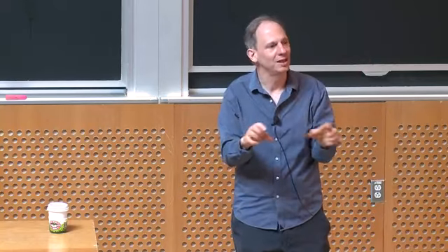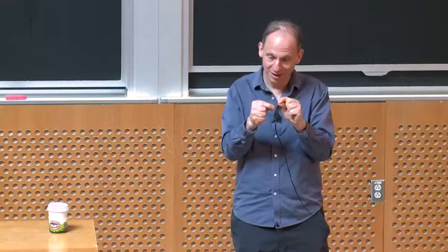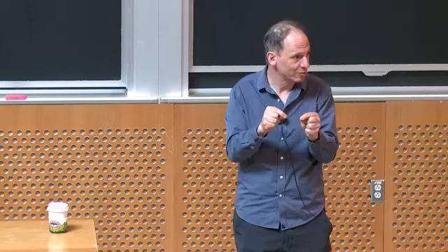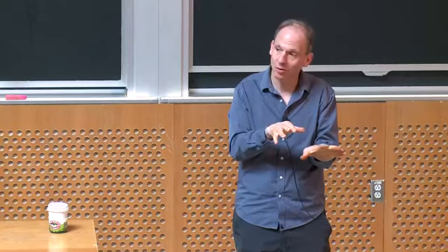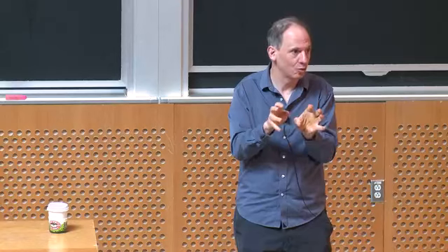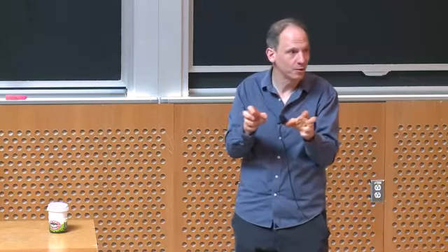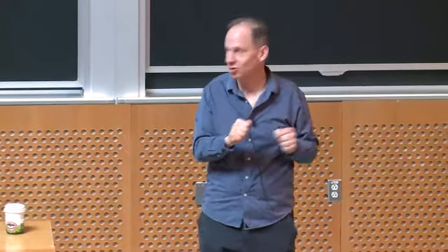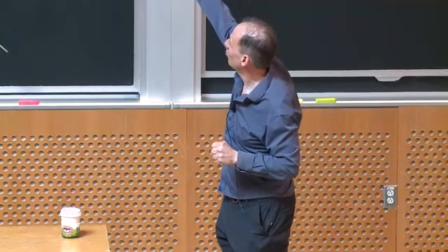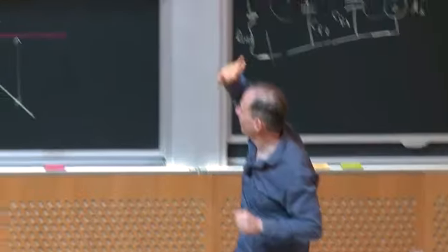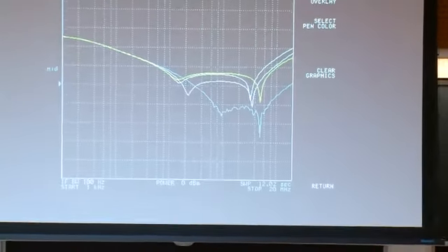Try to reduce the parasitics by being very careful about how you lay out your components. Low inductance insertion, low capacitance across the components, and that will go a long way towards getting around weird anomalous behavior and getting to be as good as you can. And even when you do that and you're getting some worse performance, getting worse around 20 megahertz, fine. Now we'll cascade another filter stage to handle the higher frequencies.